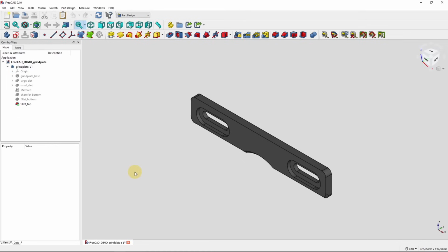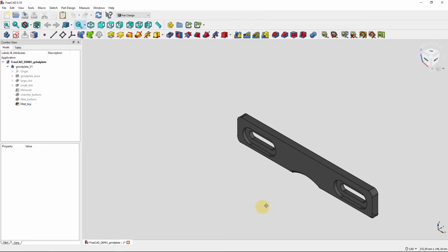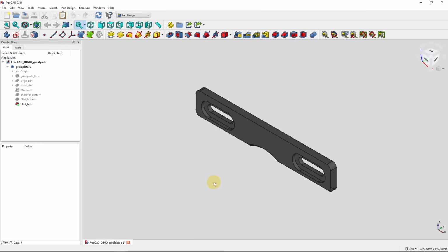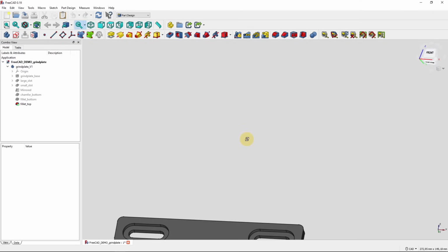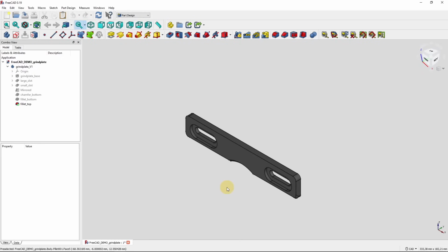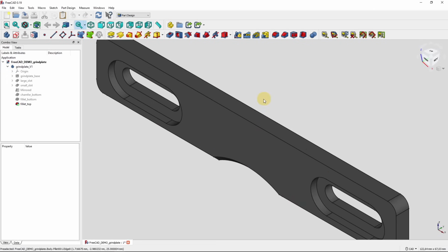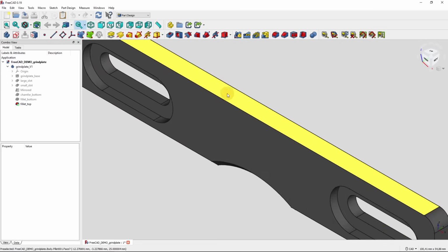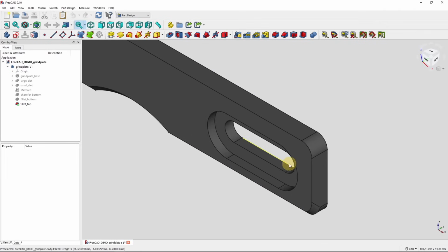So we start panning. I press the middle mouse button and I can pan my object here in the 3D view. I press middle and right mouse button at the same time. I can rotate around my object here. And if I want to zoom, I just roll the mouse wheel back and forth, and so I zoom to certain elements. The focus point on the zoom is always defined by the location of your cursor.